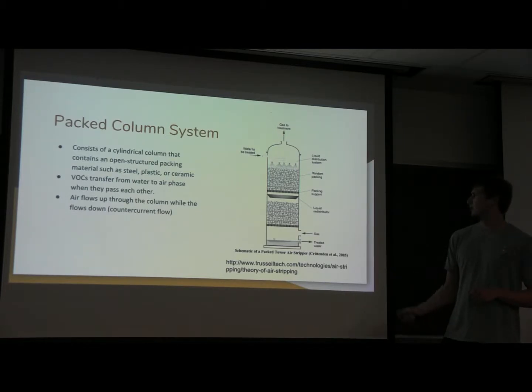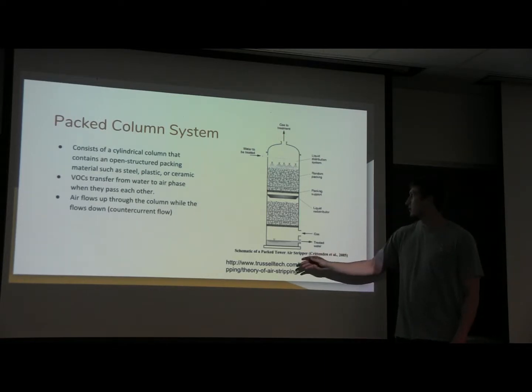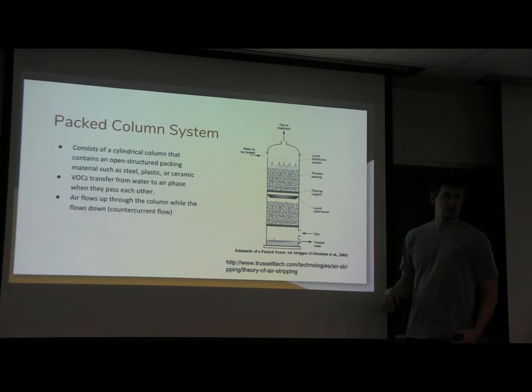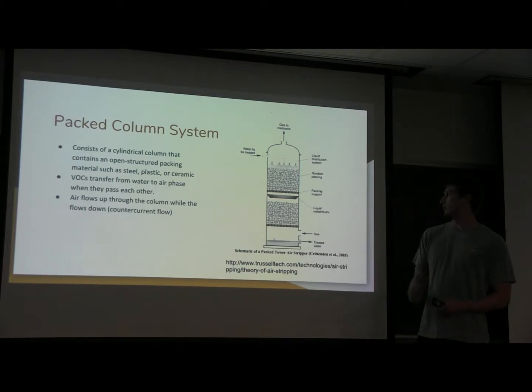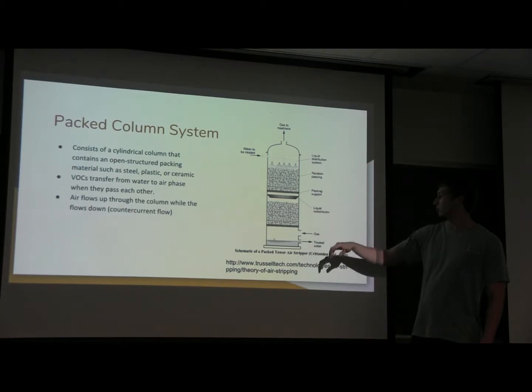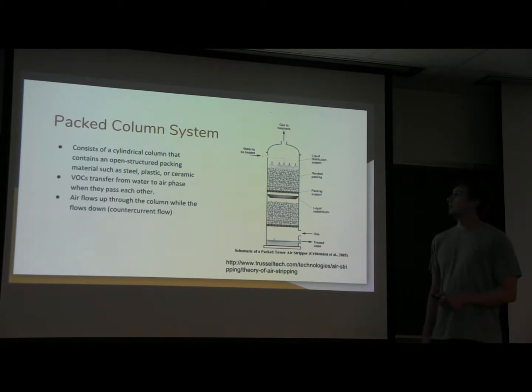removal. This system uses a countercurrent flow, so you have air coming in this way versus water coming down this way. Then the contact of the air with the water removes the VOCs, and they exit out the top while the treated water comes out the bottom.